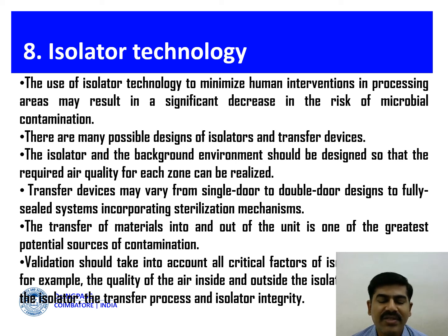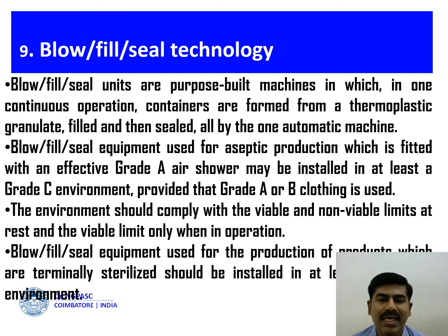So the transfer devices may vary from single door to double door designs to fully sealed systems incorporating sterilization mechanisms. The transfer of materials into and out of the unit is one of the greatest potential sources of contaminations. In blow fill seal technology, the units are purpose-built machines in which in one continuous operation containers are formed from a thermoplastic granulate, filled and then sealed, all by one automatic machine.